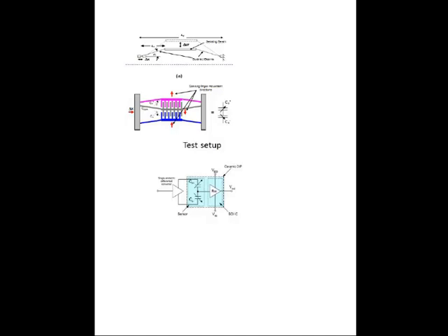And in our test setup, basically we have a ceramic dip. We place our trans-resistance amplifier, and this is our sensor, and we use an external single to differential converter, and we applied our signal here.